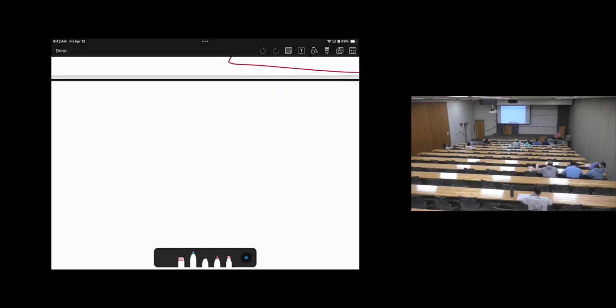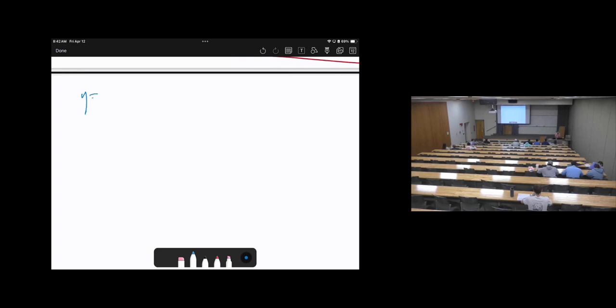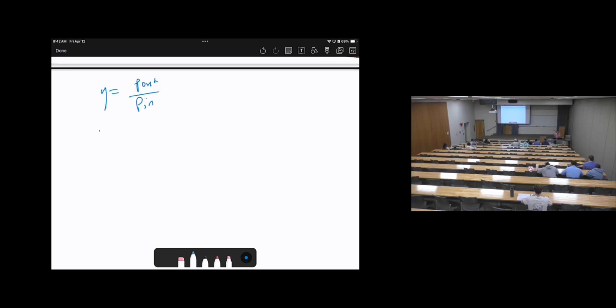So how to calculate the efficiency? According to the worksheet, it is P out over Pn. Keep in mind, all of them must be real numbers. If they are non-real numbers, then there's something wrong in your calculations. So what's P out? P out equals load torque times omega r. Load torque we calculated as 355.3 times omega r 188.5. Keep in mind, it is load torque, not developed torque.